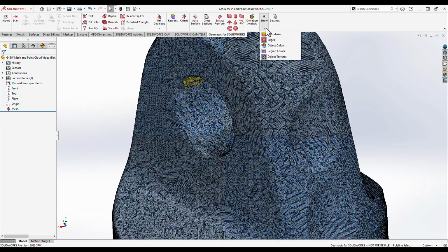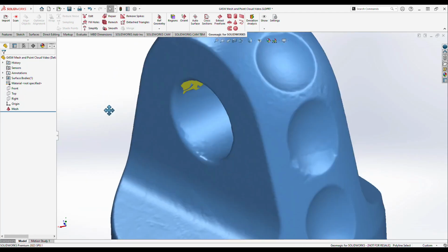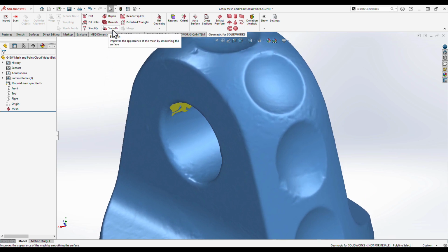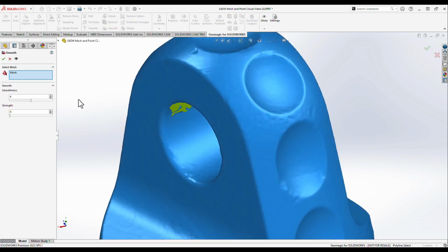The smoothing function is fairly self-explanatory. By running a remesh function before smoothing, the smoothing tool has been given a clean, evenly triangulated mesh of smoothing control points. Smoothing meshes with high-density, evenly spaced triangles tend to get much more desirable results than meshes like the previous one with scanning artifacts and triangle inconsistencies.